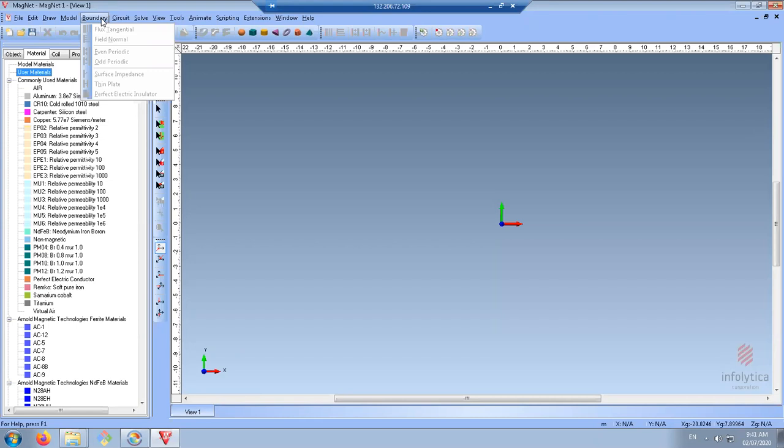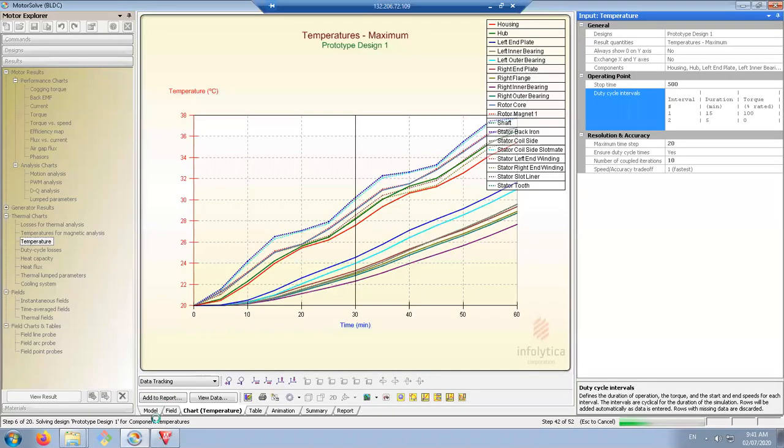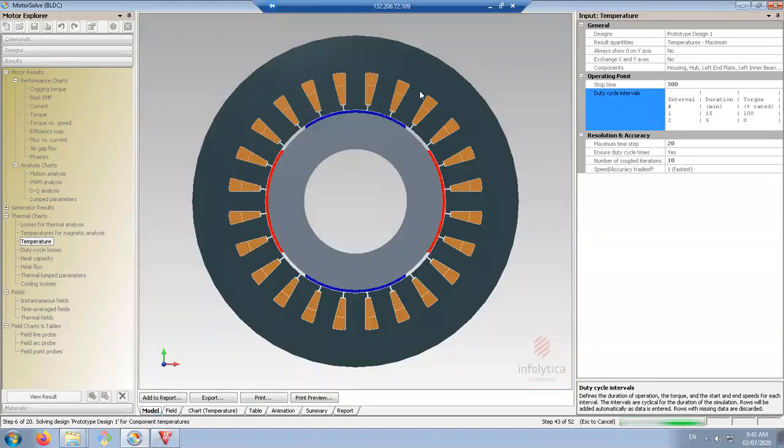For example, you have a motor, like the motor that we used in our MotorSolve model. Let me show you an example here. For example, this motor, right? This motor has 4 poles, right? So you can easily cut one pole and just simulate that one single pole, which actually consists of 90 mechanical degrees of this structure, from this point up to this point.